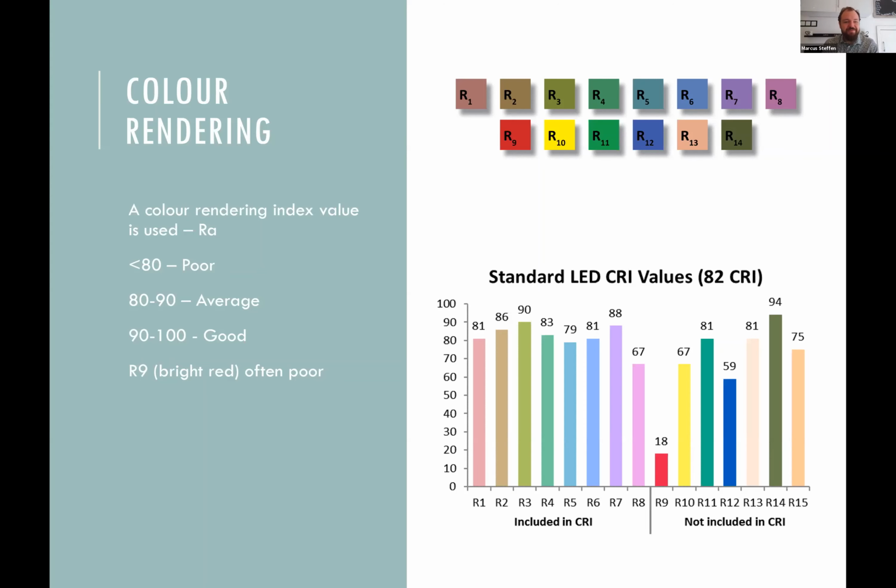But this has been causing some problems in determining good products and being able to actually compare good products between different areas. Now, when we look at different color rendering, we have to look at the project. It depends on whether or not we need good color rendering on it. So if you're doing something where you've got to display products, where the finish is important, then we will increase it and make sure we have a really high color rendering index.